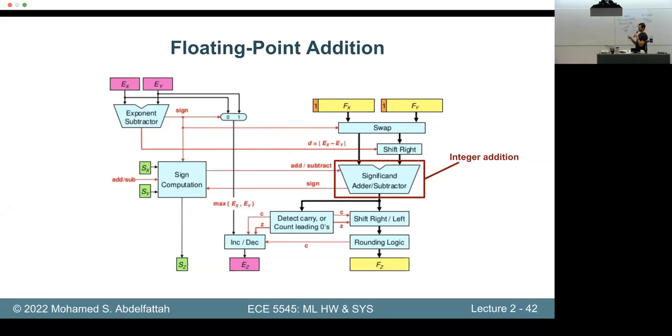So I think you add the exponents, you multiply the mantissas, you do some shifting in the end, and that's it. But here there's so much, you need to align the numbers beforehand before you do the actual integer add. So integer add is a very cheap part of the operation. Aligning usually requires multiplexers and barrel shifters and things that we will hopefully talk about in the next lecture when we talk more about circuits. And these are very expensive in terms of hardware area and energy.